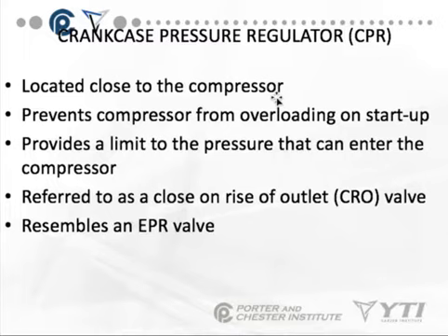And if you have a very hot case, in other words, it's been open for a while, it's been shut down, or a lot of new product is in the case that needs to be brought down to temperature, it will prevent the compressor from getting that high pressure suction as the system starts up.